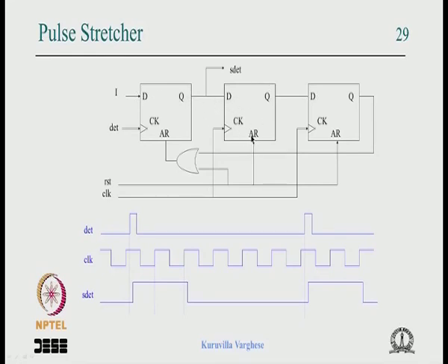with this flip flop. Maybe if you put a chain of flip flops it gets resolved. We have not seen what that timing issue is, so I am not able to discuss that now, and it is problematic. It is not a very practical circuit. Suppose you want to stretch it to 10 times a clock period, then it is not a very practical circuit.